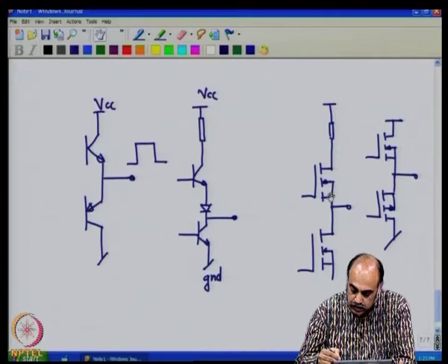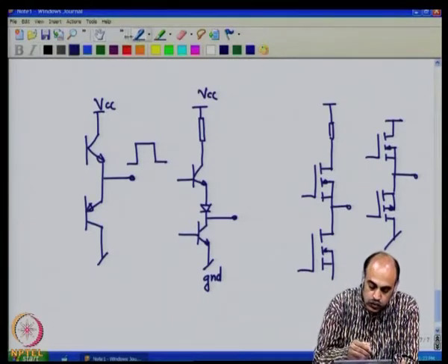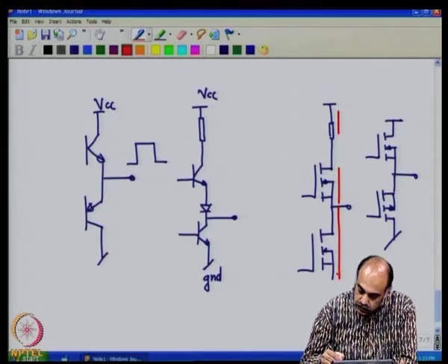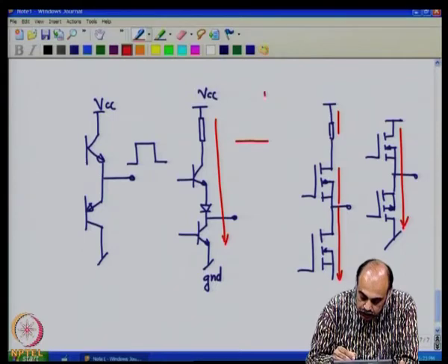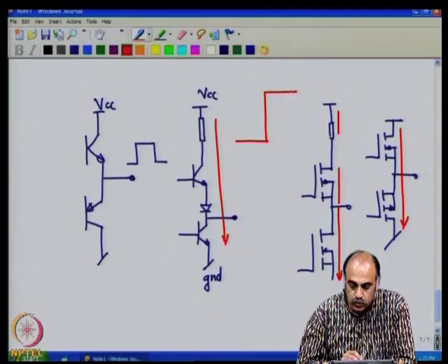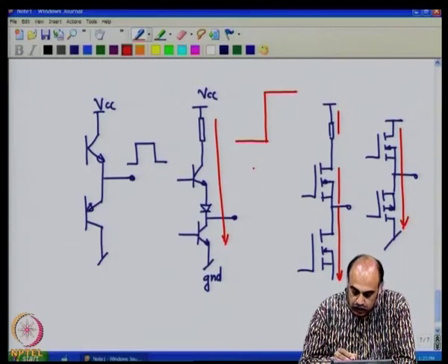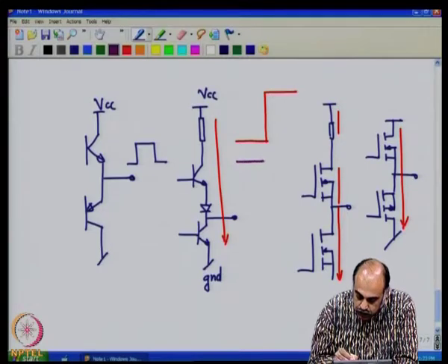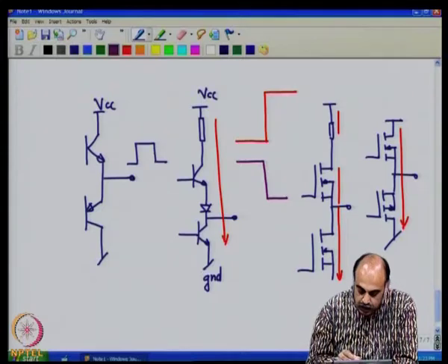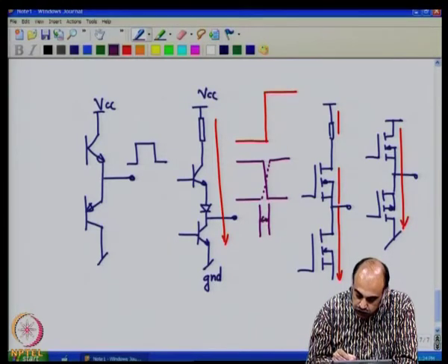During that time, the VCC is connected to the ground through a very small resistance, and during those transitions you could have a current surge or a current spike which just flows through like that. So, during a transition from low to high, the top switch, for example, which is turning on, is going from a high resistance state to a low resistance state, and the bottom switch is going from a low resistance state to the high state.